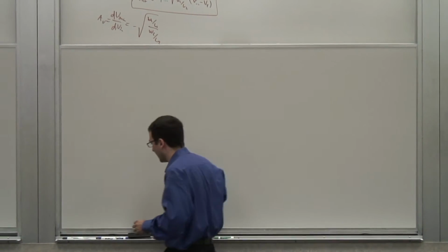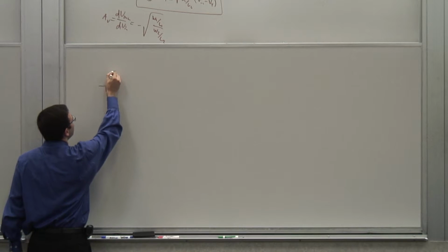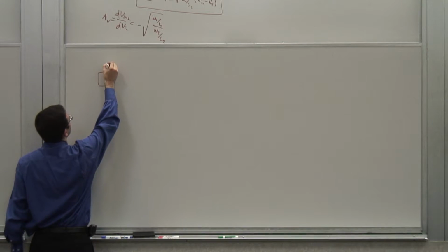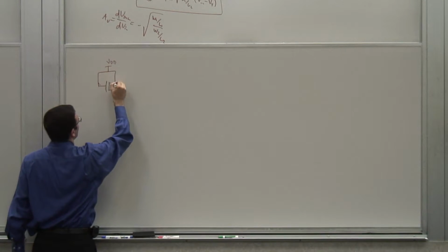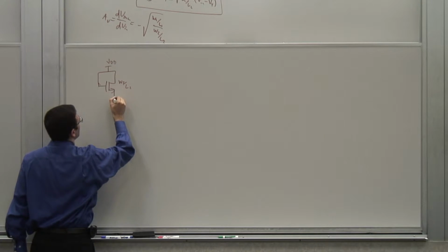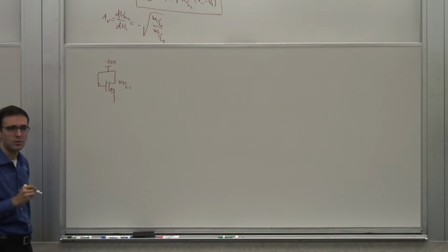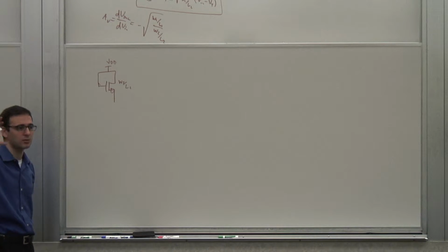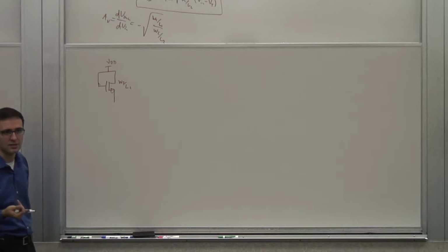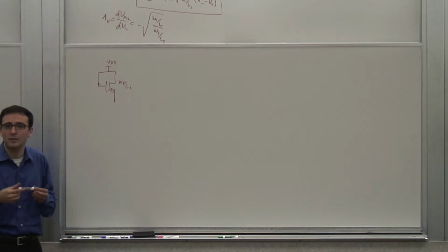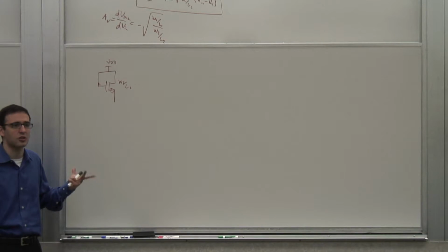Alright, so let's look at it. From a small signal perspective, what is my load? Let's look at the small signal equivalent of just that one transistor connected in the following form. We can do it for a transistor, right? It doesn't have to be just for the complete circuit. We can do it for different parts and reduce it to whatever its essential small signal model is, and then plug it into the rest of the circuit, because small signal models, by definition, are linear models.